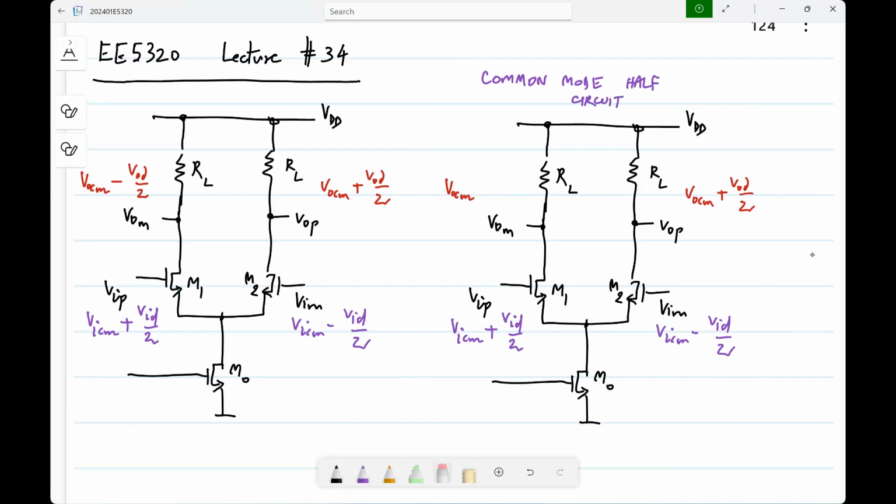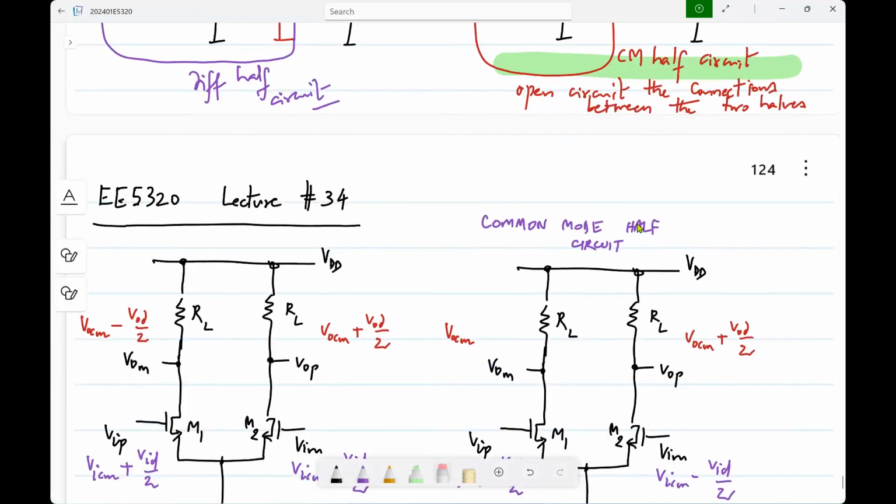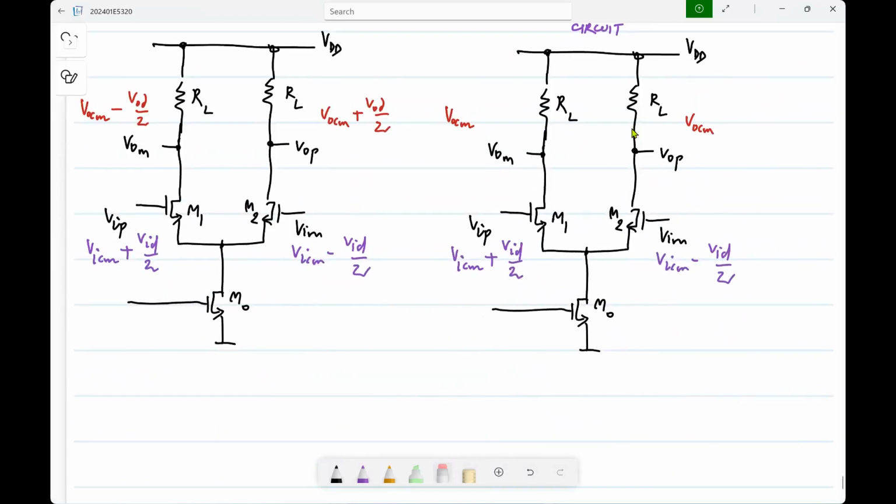I have only the common mode part of the signals. Okay. That is basically how it is, right? So now we know just by inspection that the two sides obviously have the same solution. In fact, in this case, I have marked all of them. So you can just tie the corresponding nodes together. Actually, there is only one particular node here to tie, one pair of nodes, right? This one, that's all. So you would tie these two together and do the analysis.